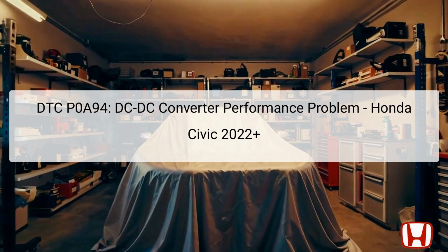The DTC P0A94 indicates a DC-DC converter performance problem, specifically related to the operation of the DC-DC converter within the Honda Civic 2022 Plus. This DTC is triggered when the powertrain control module, PCM, detects abnormal behavior or failure in the DC-DC converter, which is essential for converting high-voltage direct current to the appropriate voltage needed to power various vehicle systems. If the PCM receives information that suggests a failure, it records this DTC for troubleshooting purposes.